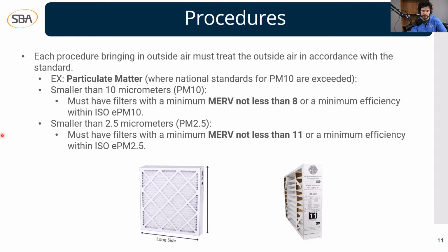So for example, say you're designing an office building downtown near a freeway. You check the EPA database or you pull sensor data and realize that the PM2.5 is regularly above safe levels. Now that's a signal, right? We need to bump our filters up to a MERV 11. Maybe we add a UV or a carbon filtration if our VOCs are a concern.